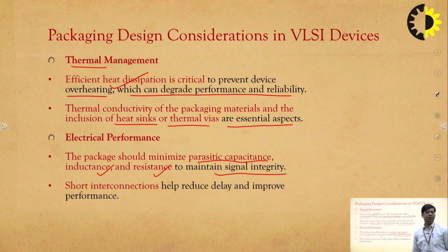Otherwise, if we have a large value of these parasitics, be it capacitance, inductance or resistance, it will compromise the signal integrity and the device may fail. So, for that, one thing that can be done is short interconnections that help reduce the delay and improve the performance.